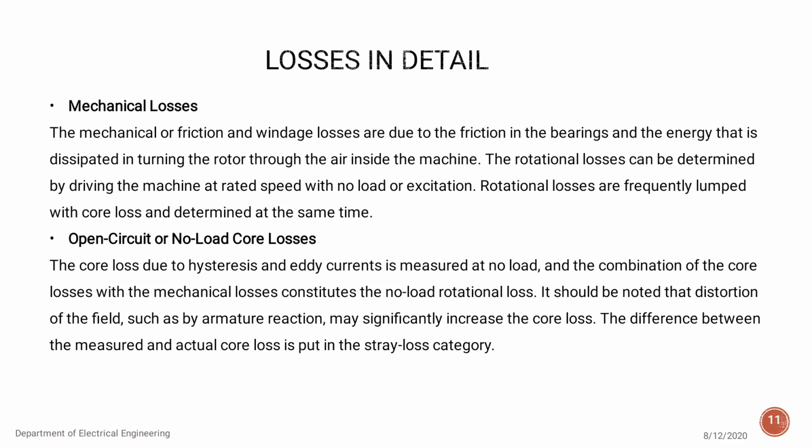To find out the mechanical as well as frictional losses, or rotational losses, we can determine them by one experiment, where we run our machine at rated speed without any load, without any load or excitation. At that time we will find out the rotational losses.